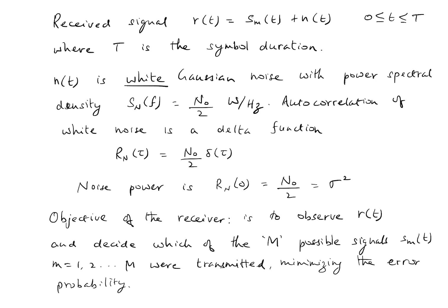So since we are talking about zero mean Gaussian noise, the power here also represents the variance, or vice versa. The variance represents the average power when the mean value is 0. So now we have all the information about the received signal, the transmitted signal, and the noise signal.